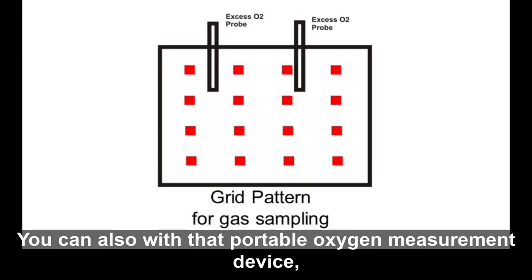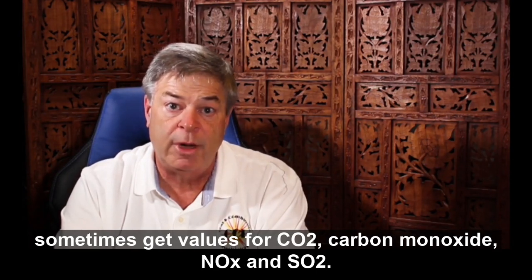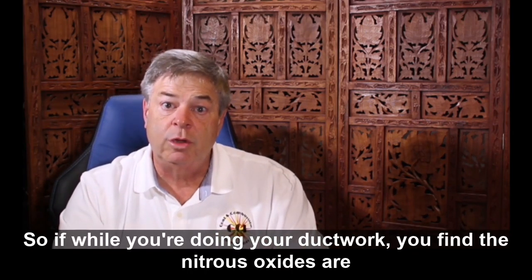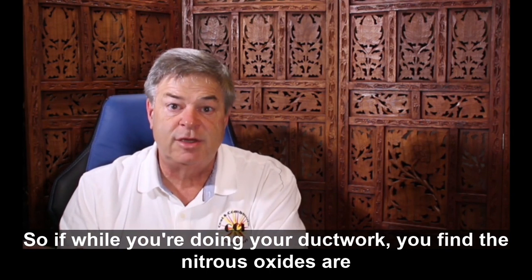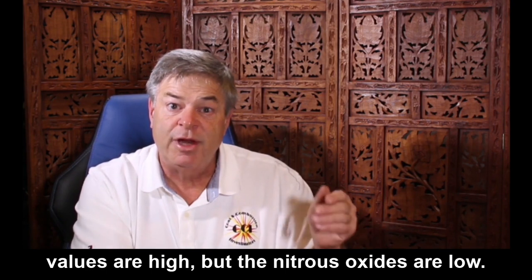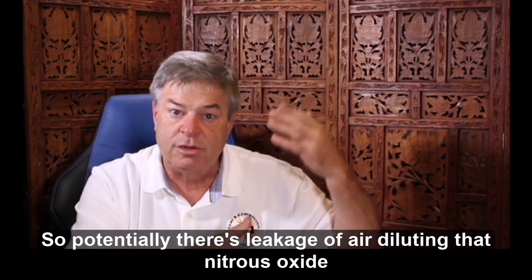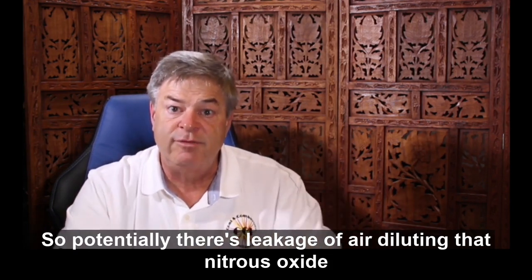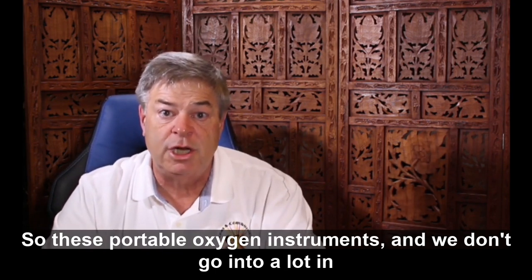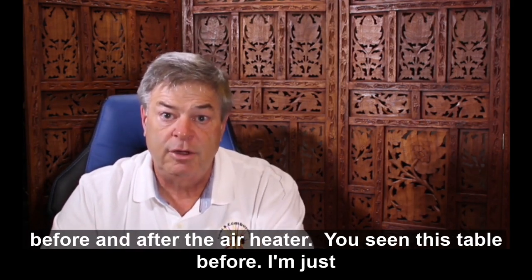You can also, with that portable oxygen measurement device, sometimes get values for CO2, carbon monoxide, NOx, and SO2. So if while you're doing your ductwork you find the nitrous oxides are high when the oxygen is low, and then you go over here and the oxygen values are high but the nitrous oxides are low, that doesn't make very much sense from the combustion standpoint, so potentially there's leakage of air diluting that nitrous oxide value. So these portable oxygen instruments, and we don't go into a lot in this class, but this is where you're going to get your better oxygen values both before and after the air heater.